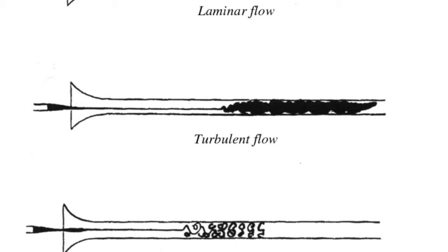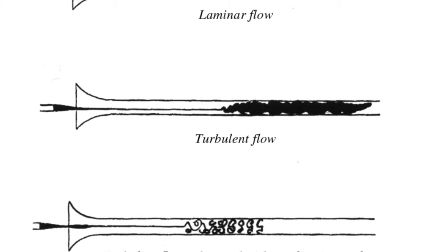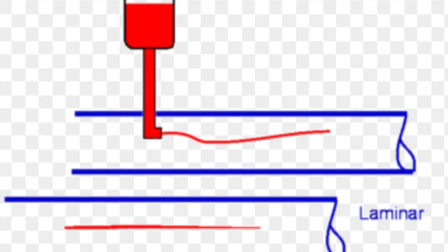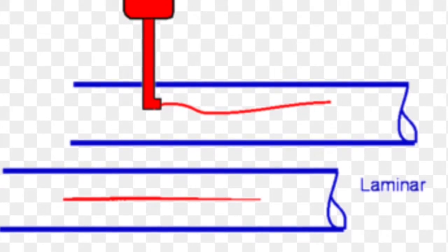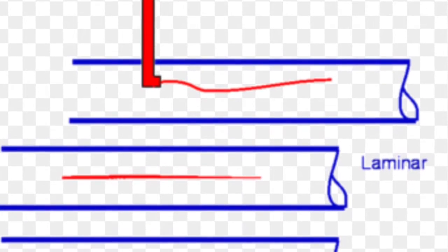Reynolds' experiment examined the water flow in a large glass pipe, and then after visualizing the flow, he injected a small vein of dyed water into the flow and observed its behaviors at different flow rates. In this experiment, he demonstrated the existence of two different flow regimes, one called laminar flow and two called turbulent flow, which are both separated by a transition phase.